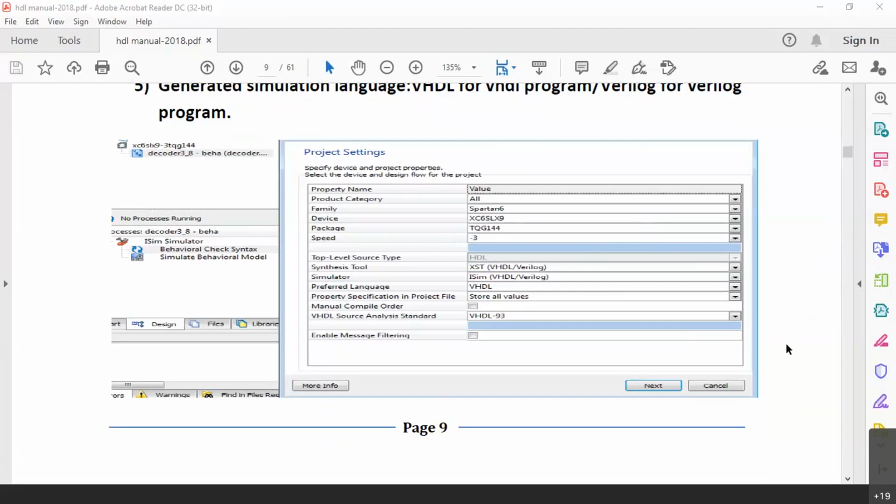Because it is a small chip, it will not have a single supply pin, it will not have a single ground pin. It will have multiple supply pins, multiple ground pins. Because supply and ground have larger current flow. But as the chip is very small, if it is given with a single pin, that single pin will get damaged. So for that purpose, supply and ground will have multiple pins.